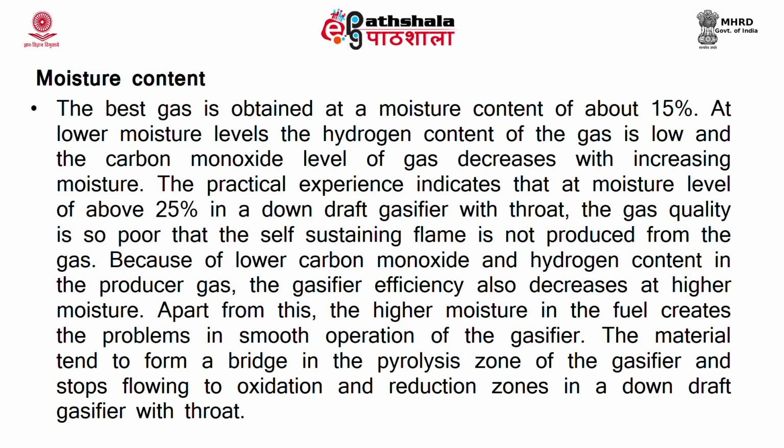Because of lower carbon monoxide and hydrogen content in the producer gas, gasifier efficiency also decreases at higher moisture. Apart from this, it also creates problems in smooth operation of the gasifier. The material tends to form a bridge in the pyrolysis zone of the gasifier and stops flowing to the oxidation and reduction zone in a downdraft gasifier.